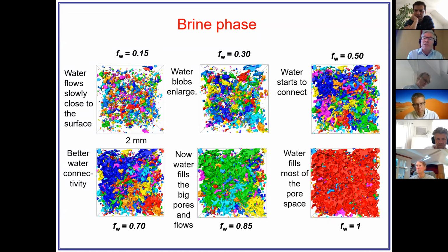So we're going to show actually that the water relative permeability is surprisingly low. And the reason is shown in this diagram: you start injecting water, it's mixed wet, the water can go in some of the microporosity and some of the small pores, but there's not much flow there. So in the end, the water has to start going into the bigger pores that are oil wet. It likes the big oil wet pores.